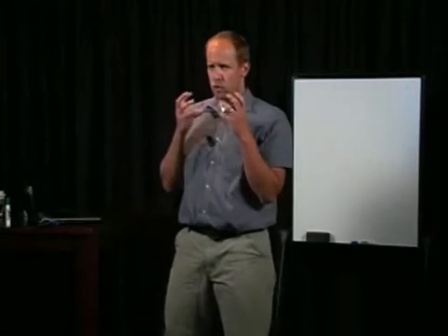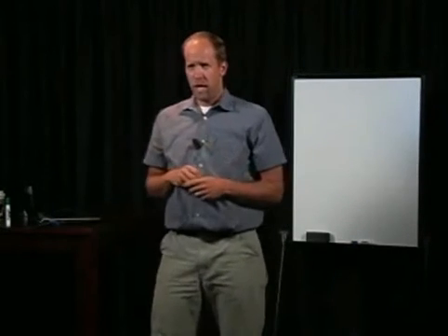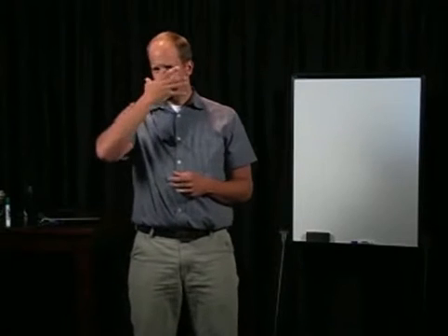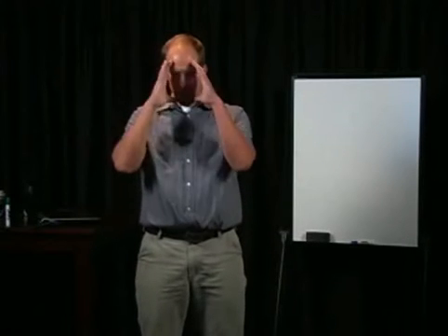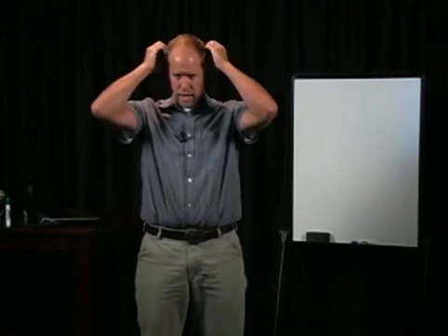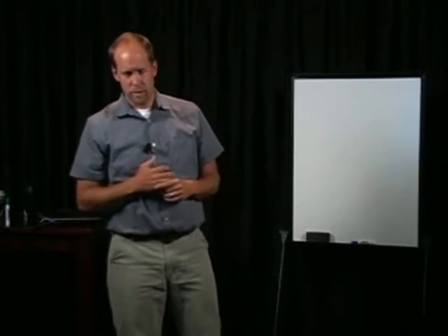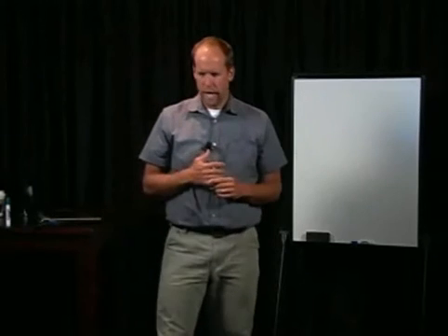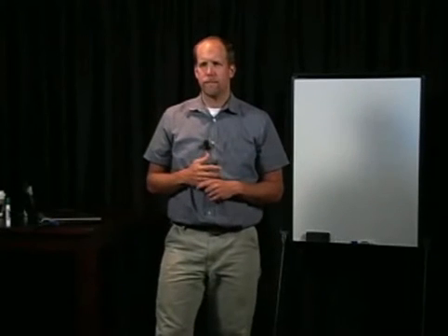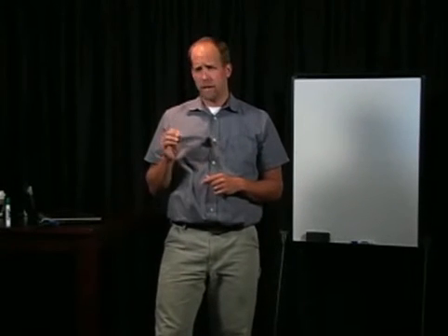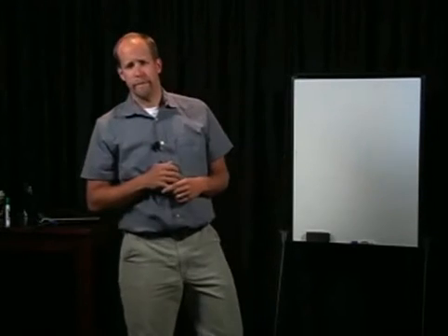A full face respirator has dual cartridge attachments. There's a full field of vision provided. It has a sealing flange and a head harness. It provides the greatest protection. This mask is best for mold inspection work and remediation work. A mold inspector, particularly inside a crawl space, should wear a respirator.